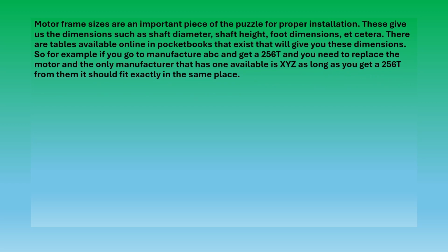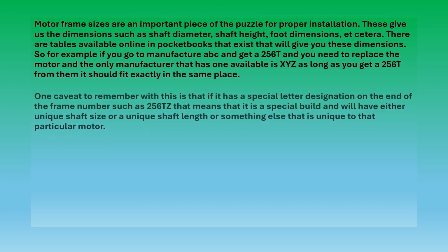Motor frame sizes are an important piece of the puzzle for proper installation. These give us the dimensions such as shaft diameter, shaft height, foot dimensions, etc. There are tables available online and in pocketbooks that will give you these dimensions. So, for example, if you go to manufacturer ABC and get a 256T and you need to replace that motor, and the only manufacturer that has one available is XYZ, as long as you get a 256T from them, it should fit exactly in the same place.